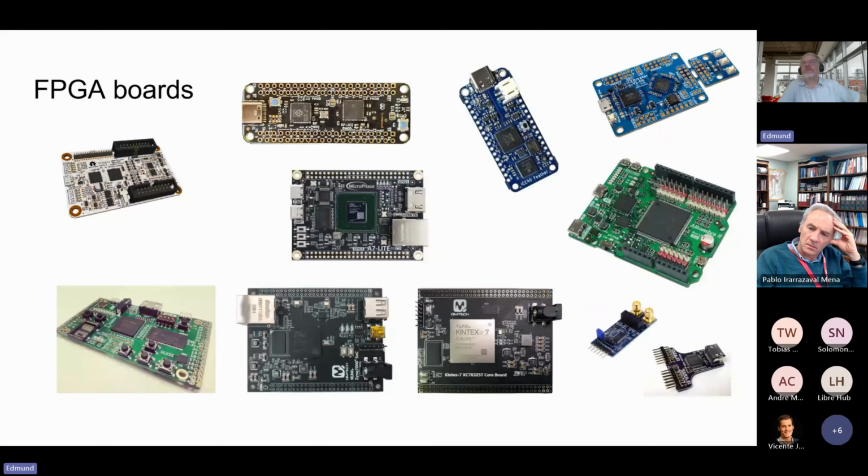And those boards can be put on a breadboard and connected up with wires, or the pins could be soldered on, or put on an additional board. The limitation here is that the speed for each pin is usually limited to 100 megahertz or 100 megabits. So these kinds of boards are not suitable for high speed.